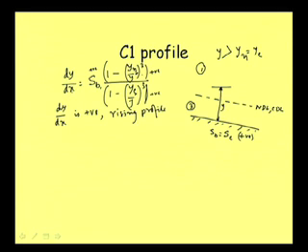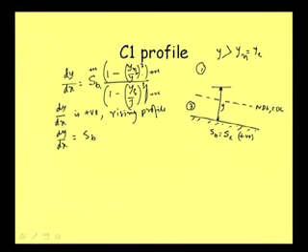So, dy/dx is positive, of course, and dy/dx is equal to SB, because this ratio becomes 1 because these two values are equal. So, dy/dx is equal to SB, what it indicates, I mean what it means physically, that we need to know. That is, you can see that this slope is nothing but SB, that is the bed slope.